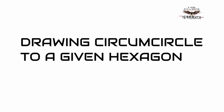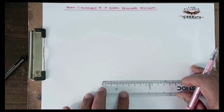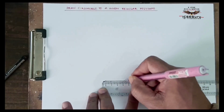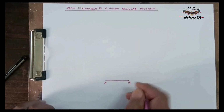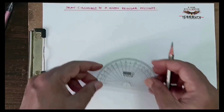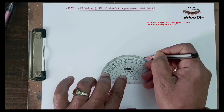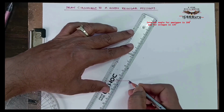To draw a circumcircle to a given polygon, which is a hexagon in this case, draw the regular polygon or hexagon. Draw the first regular side of the hexagon with given length. I took AB as 4 centimeters.